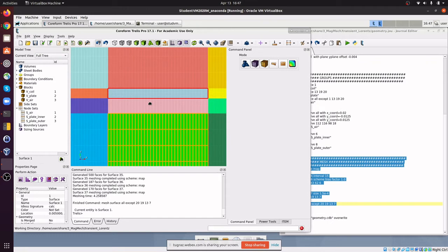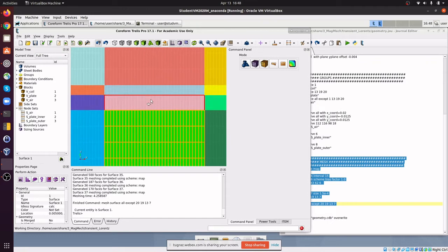As I hope you've heard in the lecture about the skin effect, the approximation of the skin depth. We need to resolve this skin depth with about 5 or 6 elements. By increasing the frequency of the excitation current in the coil, the skin depth gets smaller, since the frequency is in the denominator of the skin depth approximation.